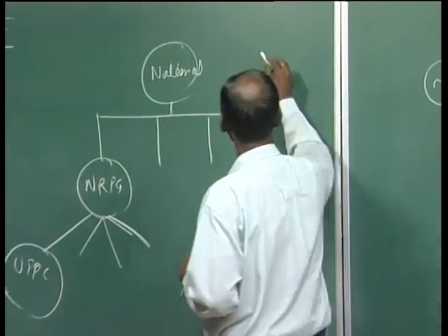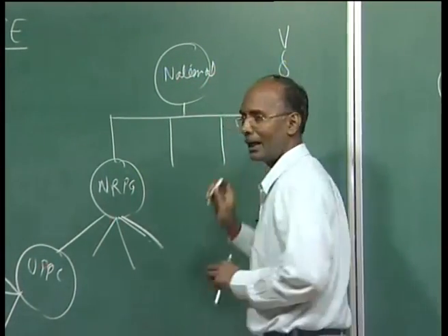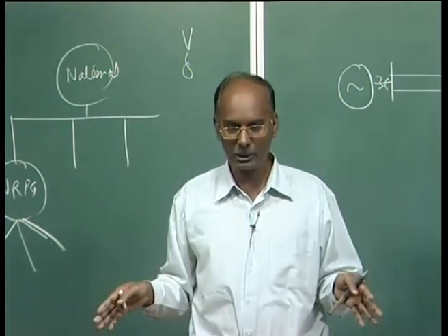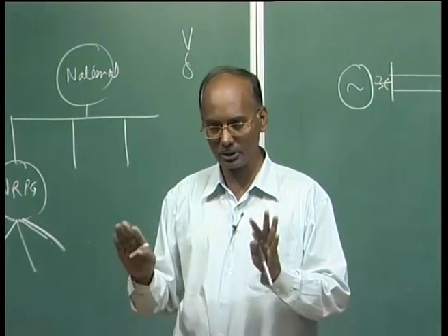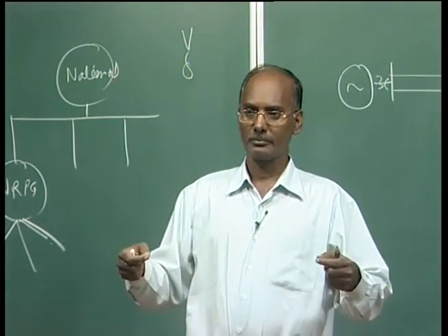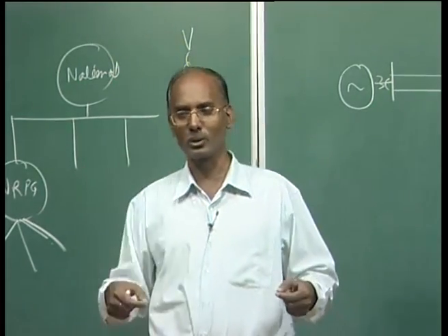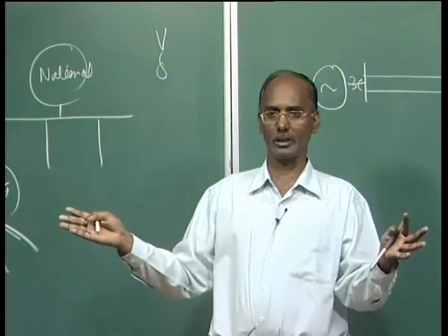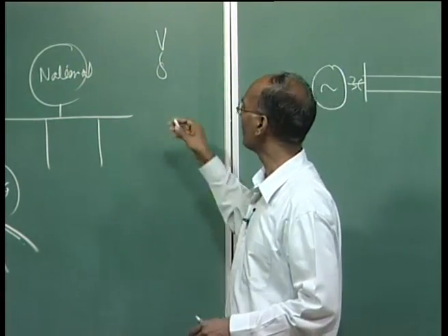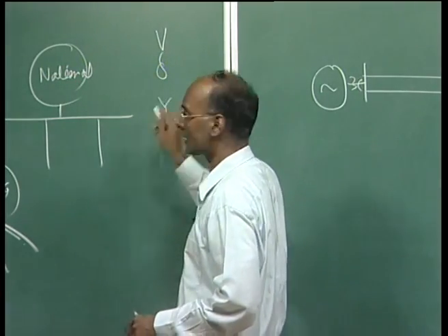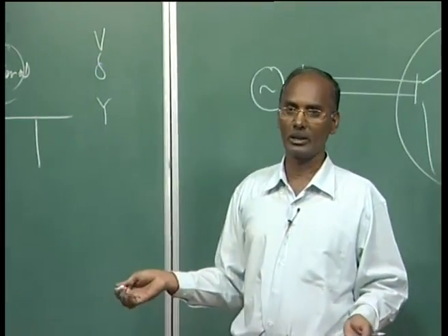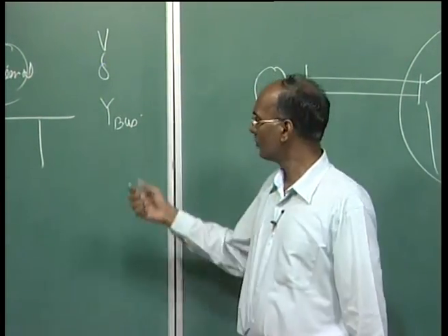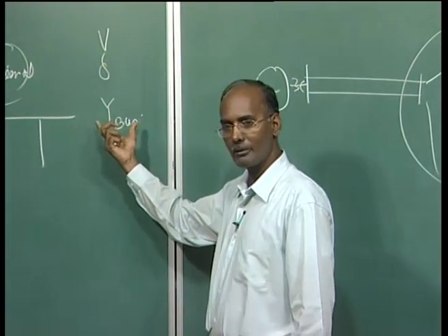So, in the load flow we normally calculate the voltage and angle. You know the network topology. Topology means you know the connectivity of the lines, transformers, generators, etc. Then you know the parameters, meaning R, X and charging etc. If there is a reactor, you know the reactor value, you know the capacitor value. All the parameters we call the topology of the system are known to you, meaning we have the admittance matrix of the network. It is normally known as Y bus.